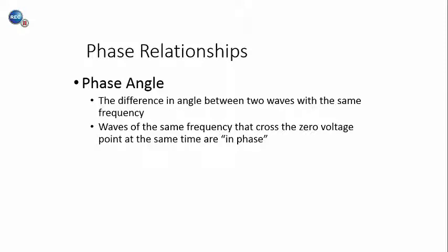And so we may have two conductors that are bent into coils, and they're rotating in a magnetic field, but when one is at 0 degrees, the other may be at 45 degrees or at 90 degrees. And so the voltage induced in those two conductors will not be in phase with one another. One of the conductors will be moving parallel to the flux lines when the other one is perpendicular. And so one will have an induced voltage while the other one does not.